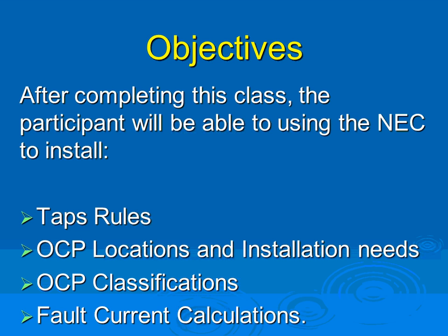I'm going to tell you as an engineer, when you size the overcurrent protection device in real life for dual element, if you use dual element time delay fuse or inverse time circuit breaker, these two, you can literally size them based for motors. You can size them 1.25, not 2.5, 1.25, and go up, and you're almost there 95% of the time.